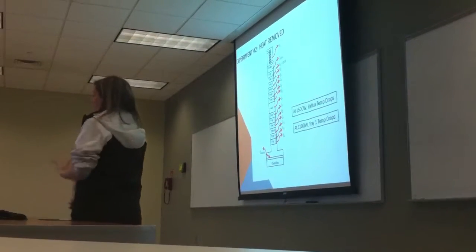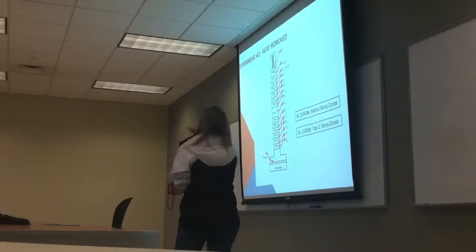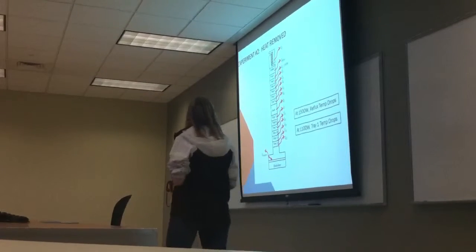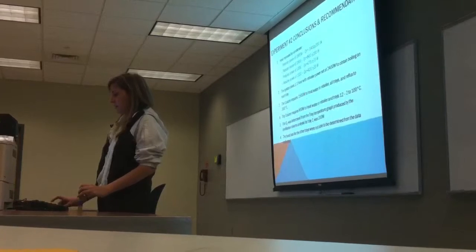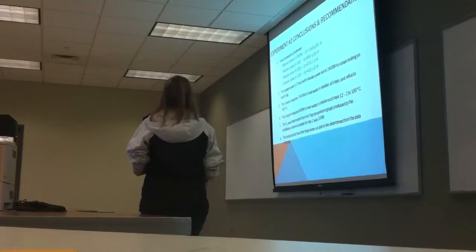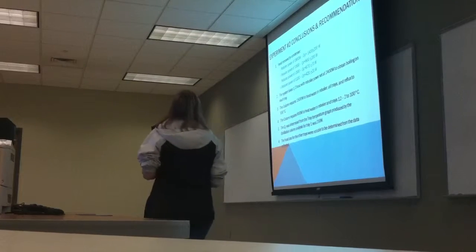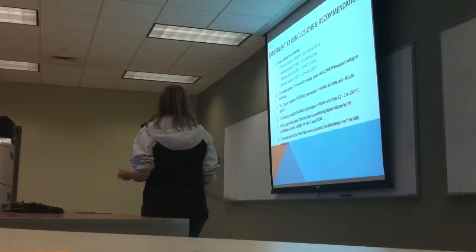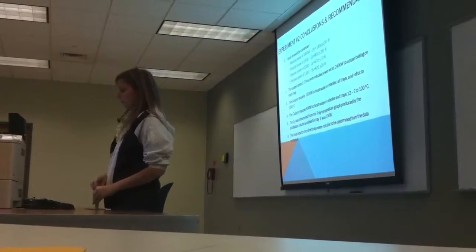Again, the schematic for the heat removed. And this one, we can only determine tray 1 because it's the only one that significantly dropped off. And it was 200 watts. So the heat removed by the condenser changes for each reboiler power setting. And then again, the system takes a half hour to achieve boiling. And the heat loss for the other trays was not able to be determined from the data that we collected.